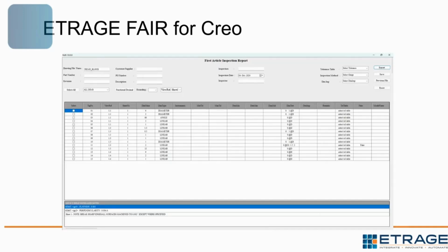Now, in addition to that, once they're ballooned, it then pulls out this UI where you can add additional information about inspection instruments, like I mentioned. You're using calipers to measure this, or CMM, or whatever it is. So you can add additional information about the inspection instruments, your tolerance tables, and any dimensional importance, so any dimensions that are critical versus basic dimensions, and things like that.